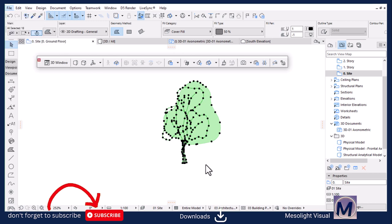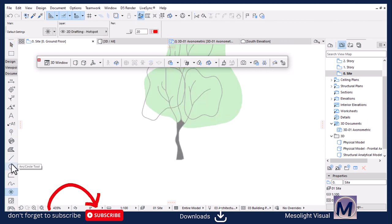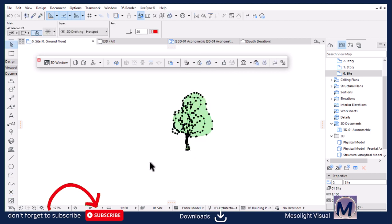But by the way, before saving it as an object, you need to have some hotspots, because objects are defined by hotspots, most especially for selection purposes. It's important to have hotspots. So if you go down here under Document, there's a hotspot tool. I'll add a hotspot here, and then there, maybe somewhere here. Yeah, I think 3 are enough. I know automatically here it will be hotspots, but it's fine. And then select everything like that.